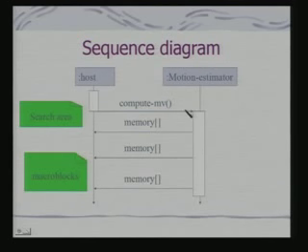On receiving the request, the motion estimator should get the data about the search area and the macro blocks. So, I need to get the memory requests onto the host. So, it implies, from the sequence diagram itself you can realize, there has to be a substantial data movement between your memory and the FPGA block.